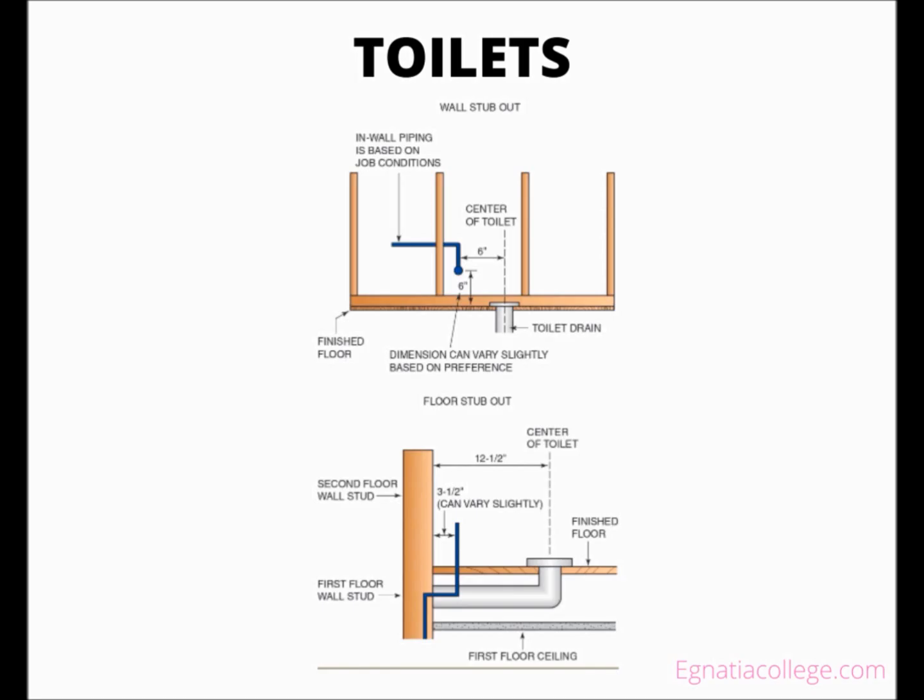A rough-in occurs before any flooring material is installed. If the floor is tiled, the plumber must install the water piping higher to accommodate the tile. The wood trim known as base molding is higher in many custom homes than spec homes. If the plumber installs the stub-out too low, the piping conflicts with the base molding. If the stub-out is too high, making the final connection to the toilet may be impossible.